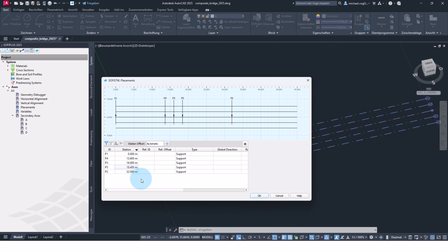To keep this tutorial compact, we will use these positions also as the border between the concreting segments in the span and the concreting segments at the inner support, and we place here also the change from the span cross section to the cross section at the support, which has a higher amount of reinforcement.